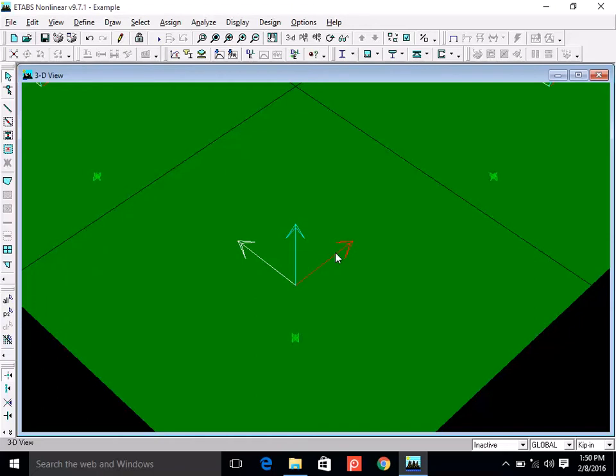For example, if you are confused about these bending moments M1 and M2, and by mistake you take them opposite, then the end result is that maybe you provide more reinforcement in that direction and less reinforcement in this direction. So it will be opposite, right? Then definitely your slab is not going to survive, or it will have cracking. So be very careful in reading these moments, because these moments are ultimately translated into reinforcement. Make sure you understand this local axis system.